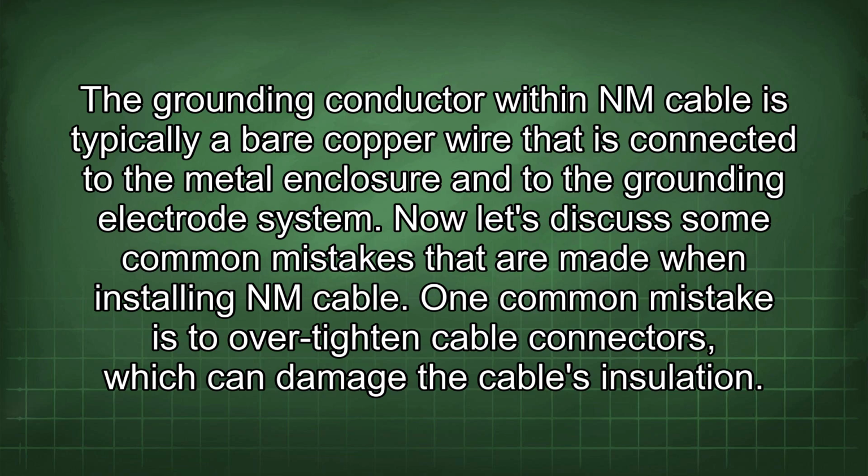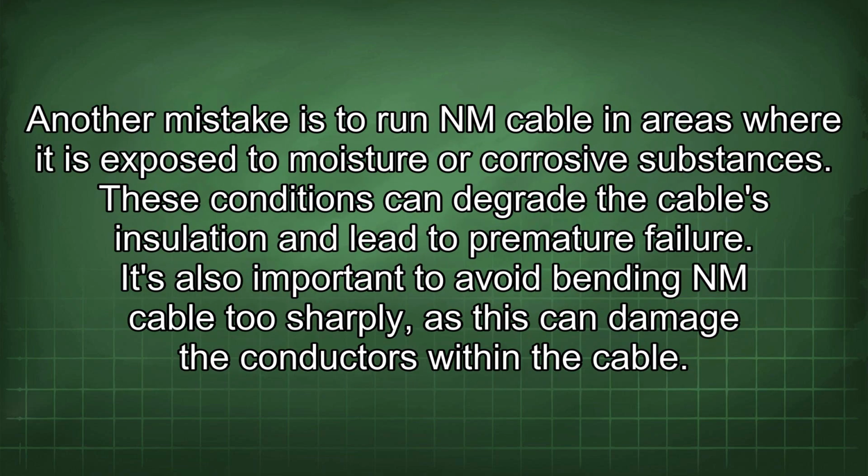Now let's discuss some common mistakes that are made when installing NM cable. One common mistake is to over-tighten cable connectors, which can damage the cable's insulation. Another mistake is to run NM cable in areas where it is exposed to moisture or corrosive substances. These conditions can degrade the cable's insulation and lead to premature failure.